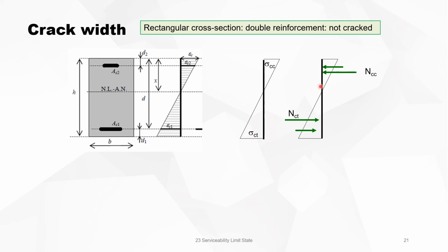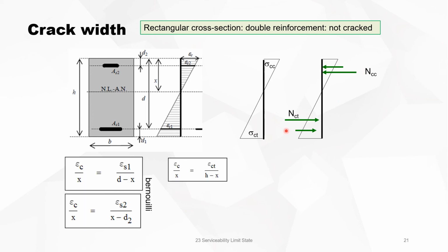These are the stresses and these are the corresponding forces: the compressive force in concrete and steel, and the tensile force in concrete and steel. We use Bernoulli.